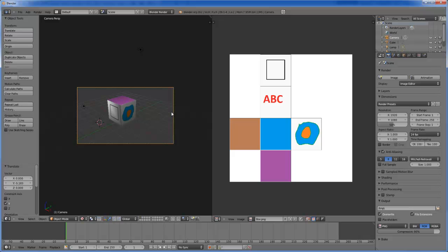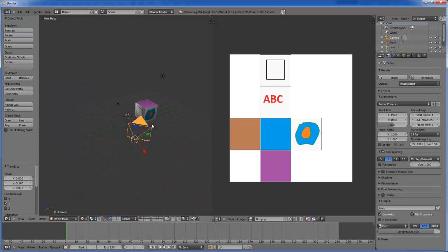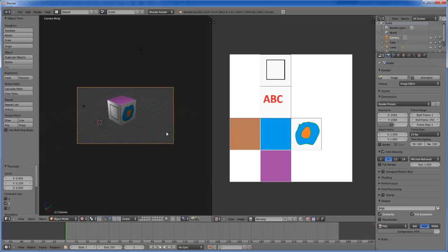The way to move the camera around, you can press 0 so that you can move the camera like this. But let me just move the camera. Move your mouse arrow here, click the right mouse button, create the frame, and before you release it, by pressing the left arrow, you can click the middle mouse button, and then zoom in or zoom out. When I'm happy with the frame, I'm going to click the left mouse button and the camera is stuck there. So let's try to render this.